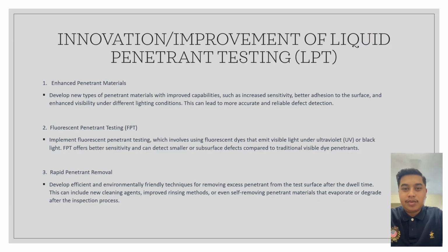Assalamualaikum warahmatullahi wabarakatuh. My name is Ahmad Syamal bin Ahmad Kamal Hilmi. So today I would like to present to you about innovation and improvement that we can apply to liquid penetrant testing. The first one is enhanced penetrant material. Develop new types of penetrant material with improved capabilities such as increased sensitivity, better adhesion to the surface, and enhanced visibility under different lighting conditions. This can lead to more accurate and reliable defect detection.